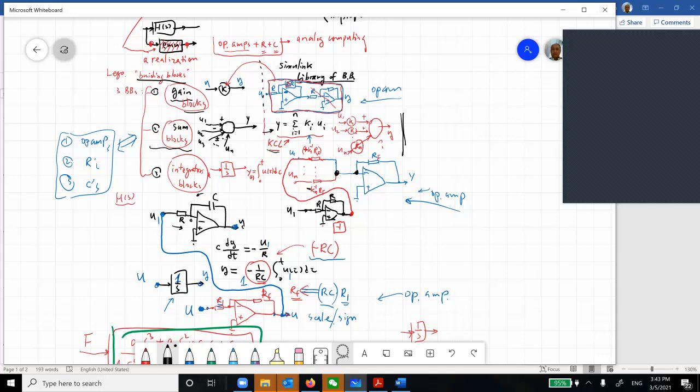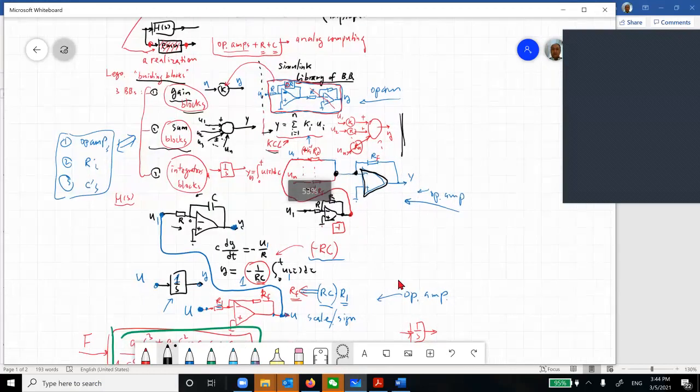But remember, you have to use Opamp, okay? If you add things together without Opamp, you short circuit, you get a spark, you may catch fire. Don't do that. Okay, so then I also mentioned how to remove this negative sign, how you can make this coefficient 1. So I think this argument is quite simple.